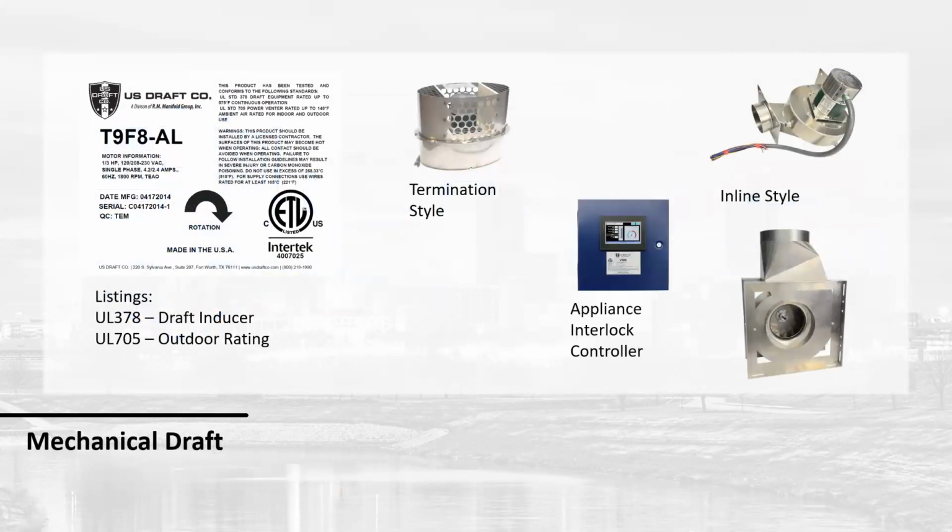We have 3 different style fans. We have a termination style fan and 2 inline fans. Everything by code must go through an appliance interlock. We can't just put a fan on there and hope for the best. We have to actually monitor the fan, monitor the pressure, and lock out appliances if there's any issues. We do have our UL listings, both 378 and 705, which is required for draft controls.